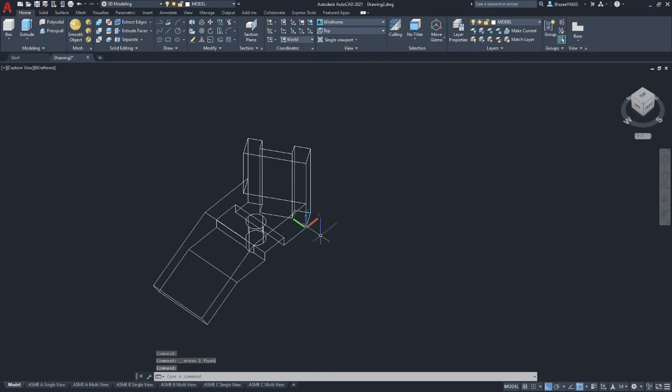So the next step is to place the hole in this face. And this is why an auxiliary view would be used. Auxiliary view looks at the face at the angle normal to it. So to define the location of the hole and the diameter, you would need to have a view on your drawing that's normal. The equivalent in CAD is your user coordinate system.